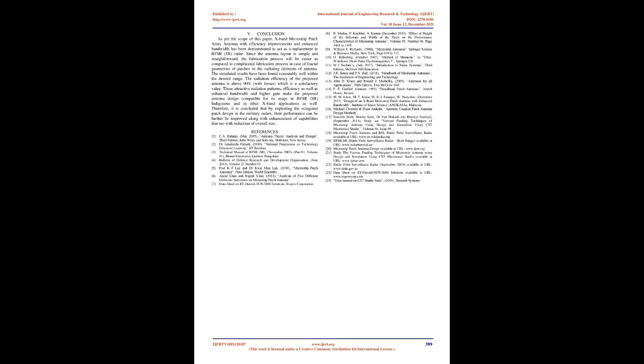The simulated results have been found reasonably well within the desired range. The radiation efficiency of the proposed antenna is above 90%, with losses, which is a satisfactory value. These attractive radiation patterns, efficiency as well as enhanced bandwidth and higher gain make the proposed antenna design compatible for its usage in BFSR, SR, indigenous and in other X-band applications as well. Therefore, it is concluded that by exploiting the octagonal patch design in military radars, their performance can further be improved along with enhancement of capabilities, that too with reduction of overall size.